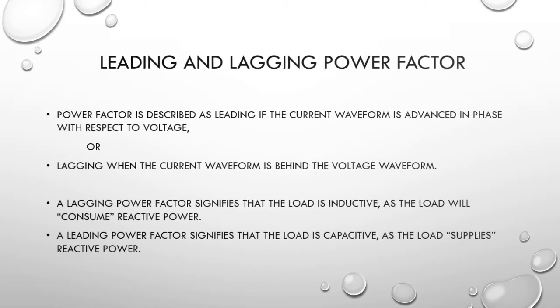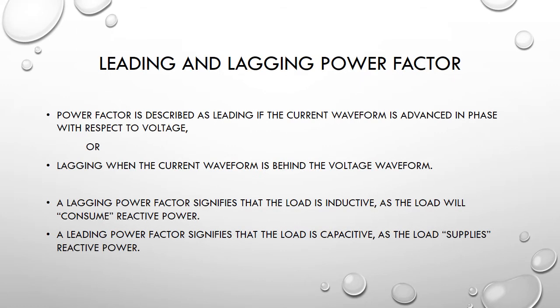So what do we mean by lagging and leading power factor? What is leading power factor? Leading, as the word suggests, means that the current waveform is ahead of the voltage. So it means current is leading voltage. It is ahead.